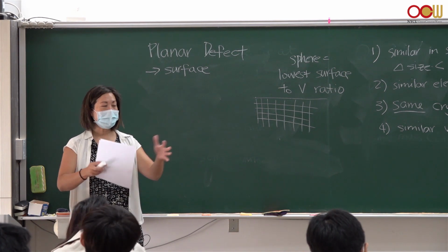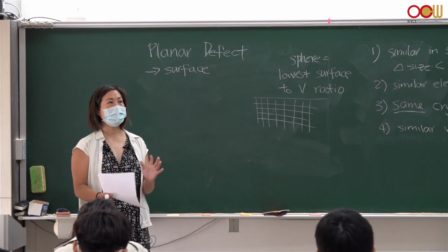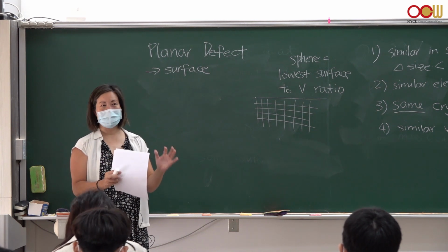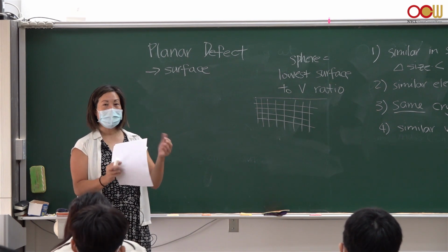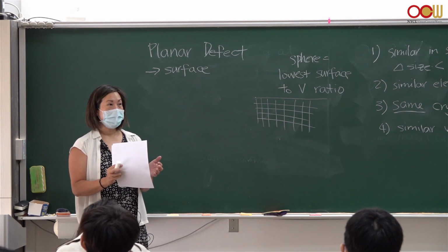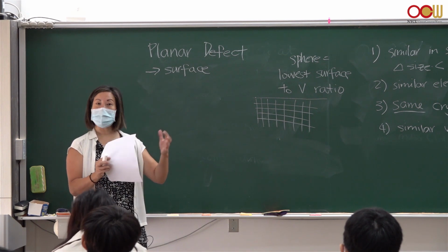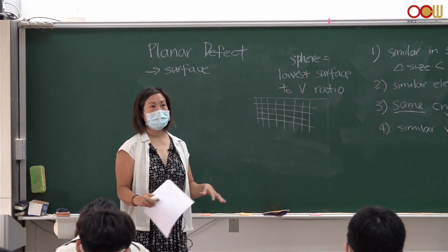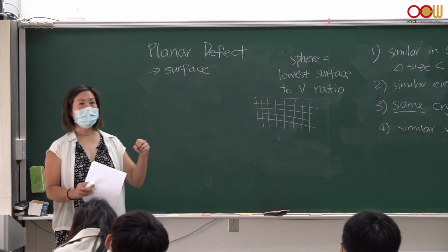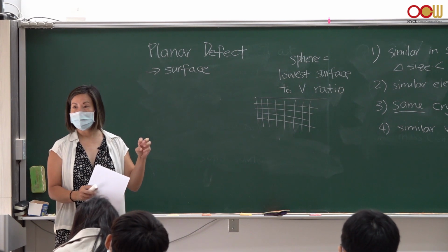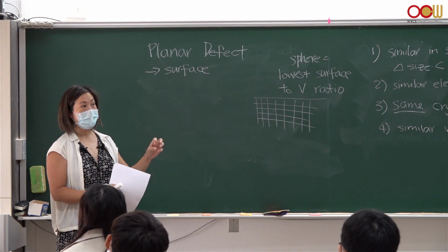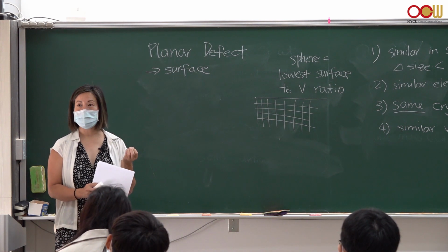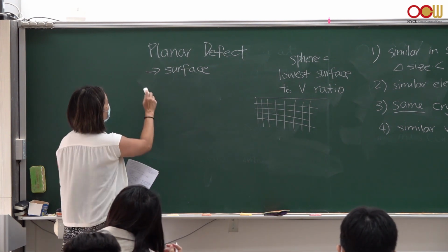So that means if you allow any material to move its shape freely, usually liquids, then the higher the surface tension, the more likely it will form a sphere. The lower the surface tension, the less driving force there is to minimize the surface, and it might spread out more evenly or easily. Things like mercury, which is a metal at room temperature but liquid, will form little spheres as well because it has a very high surface tension. Okay, so the surface is a defect.